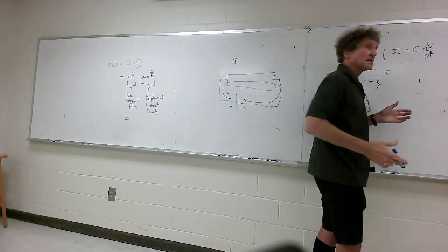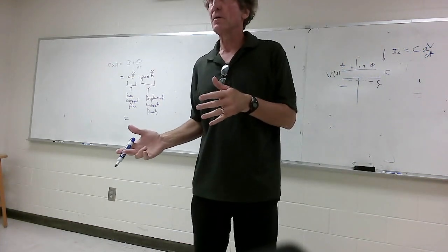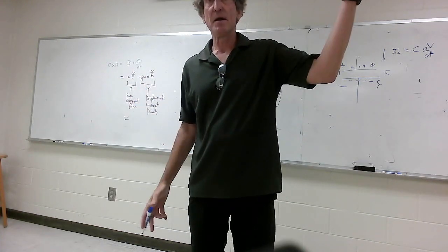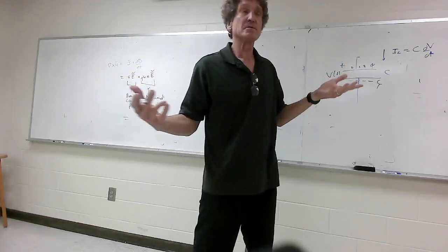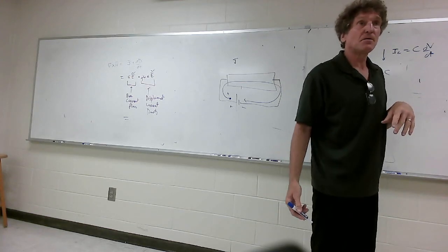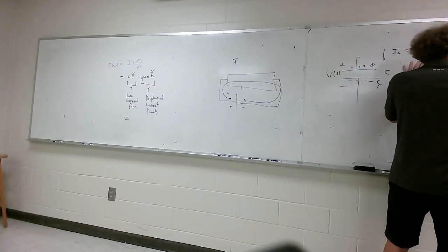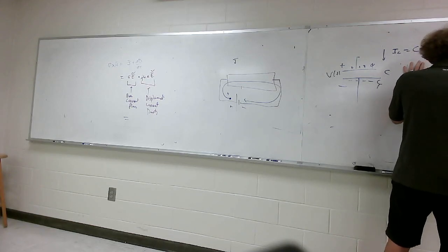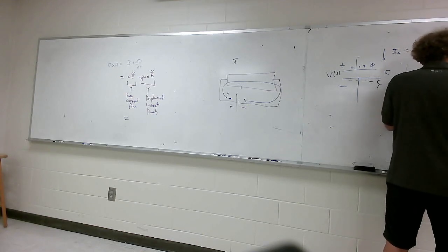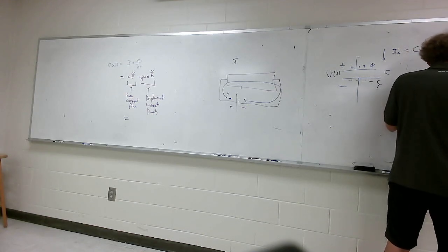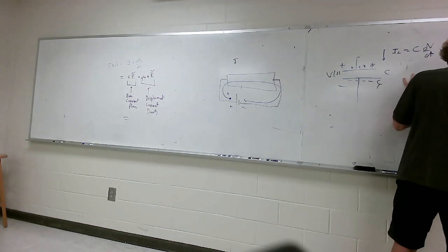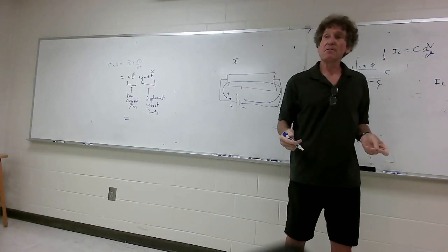Now, do you all remember this? The only time you can have flow in a capacitor is with a time-varying voltage, if it's an ideal capacitor. Time-varying voltage, like a sinusoidal. But what is it in the phasor domain? What's capacitive reactance? It's 1 over j omega C, right? So if I wanted I in a capacitor at a constant frequency, it would be V in the phasor domain divided by 1 over j omega C, or j omega C times V. Now if the frequency is 0, if omega is 0, no current.